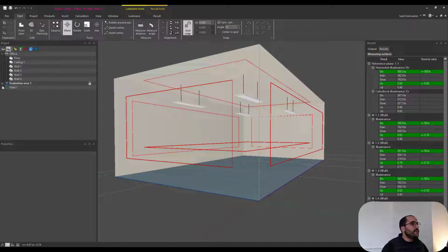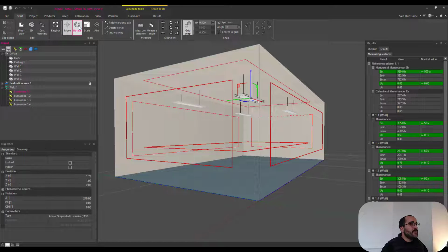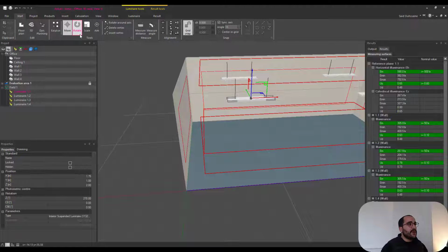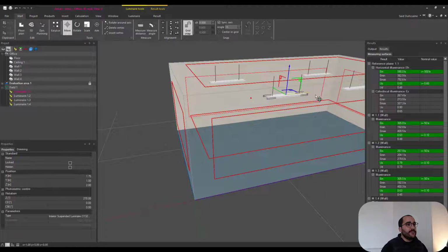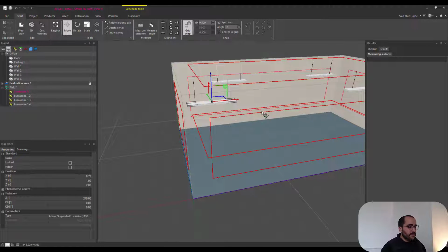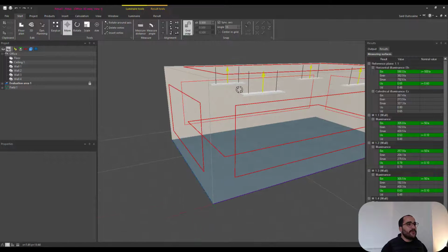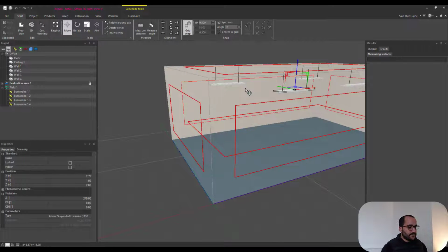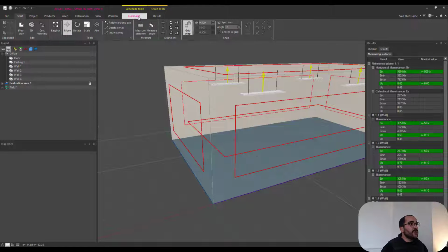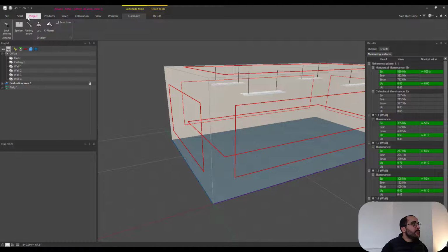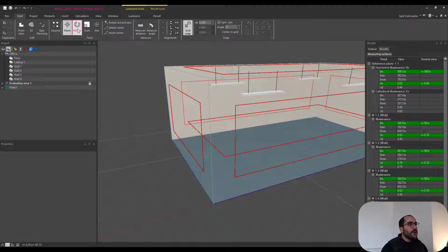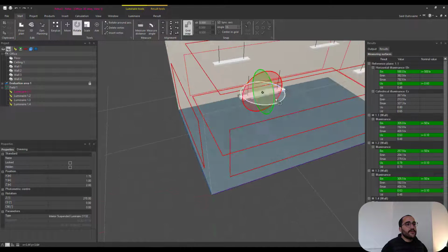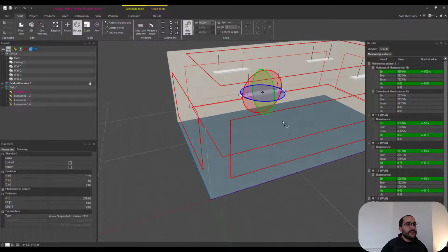And then there is move. If we go to field here, to the project, go to field, select a luminaire, the one here. When you select it, we have the possibility to move it because we are in the move tool here. We can move it like this, but then I will press Ctrl Z, go back to this position, and then I will also go back to luminaire to hide this, and then we also have rotate. We can rotate these luminaires like this.